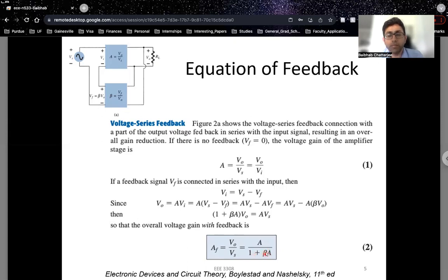The second term will be just beta because you are dividing this whole term with A. So as the first term goes away and the second term becomes beta and the numerator becomes 1, your overall gain after the feedback is 1 upon beta. That's a very interesting thing to note, because assuming that your amplification factor in the feed forward path is very high, you are able to create an amplification which is just dependent on the beta term, and overall amplification after feedback becomes 1 upon beta.